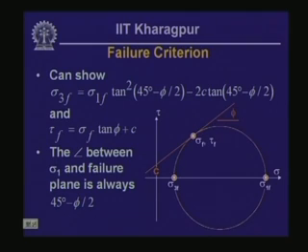And also you can show that the shear stress at failure represented by the point of tangency of the Mohr circle representing the state of failure and the Mohr-Coulomb failure envelope, at the point of tangency, tau f is going to be given by sigma f tan phi plus c, where phi is the friction angle as I indicated before, and c is the intercept, cohesion intercept, as shown on the sketch near the bottom right of this particular slide.